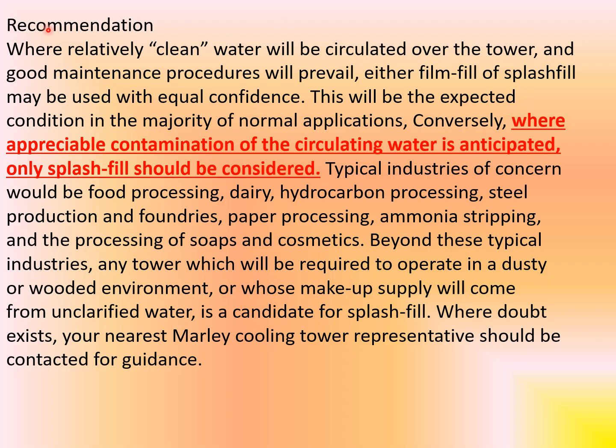Friends, here is the recommendation from the expert. Where relatively clean water will be circulated over the tower and good maintenance procedure will prevail, either film fill or splash fill may be used with equal confidence. This will be the expected condition in the majority of normal applications.